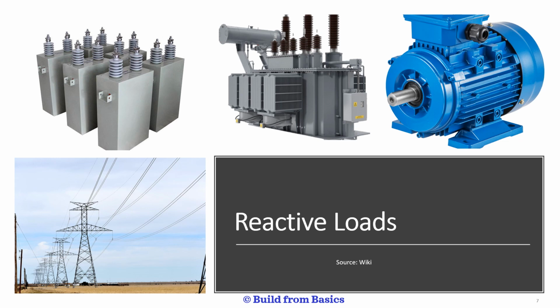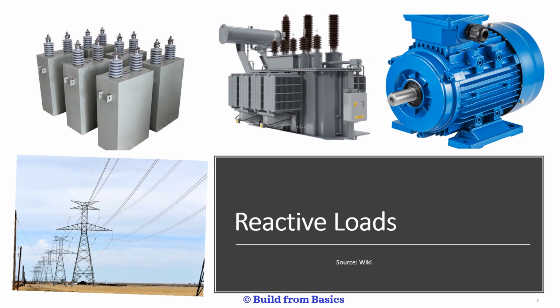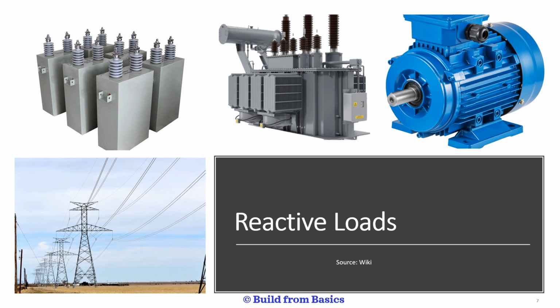Examples of reactive loads are a motor on low load or no load condition because it mainly acts like a reactive load and consumes reactive power, and also transformers, reactors in the substations, and line inductance of transmission lines. The other type of reactive load is capacitive: line capacitance of the transmission line, compensation capacitors of the power system, and compensation converters. They also act as reactive loads.